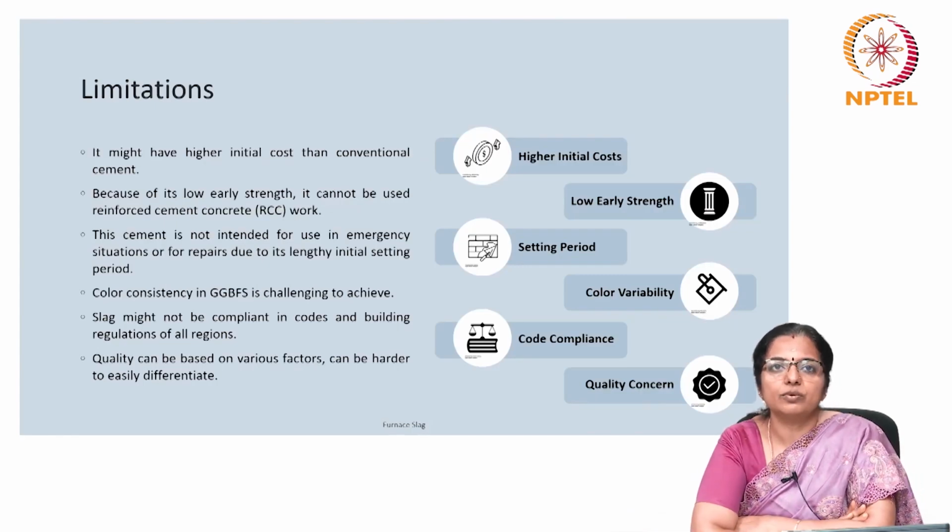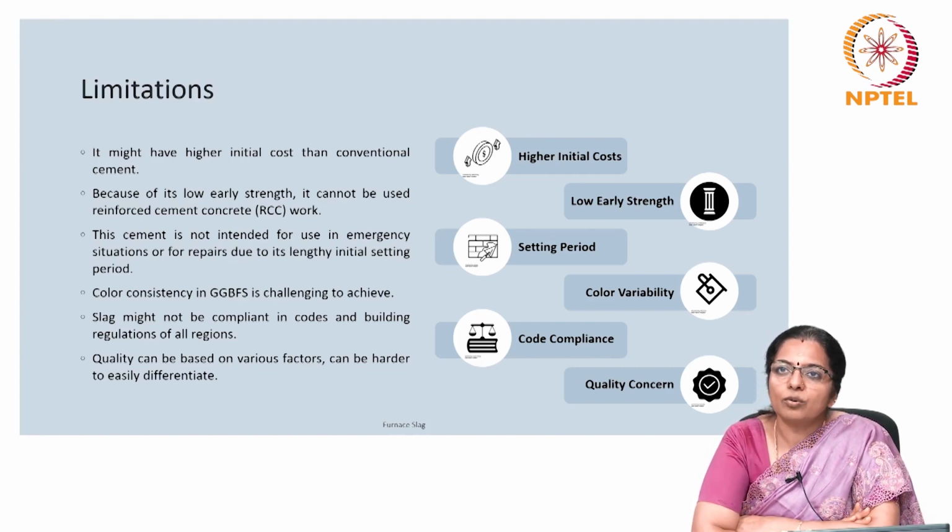Of course, it comes with a limitation. So, when considering ground granulated blast furnace slag for construction, it is important to note a few aspects. Firstly, there might be a higher initial cost compared to conventional cement. Additionally, due to its lower early strength, it is not suitable for reinforced cement concrete work, impacting certain construction applications.